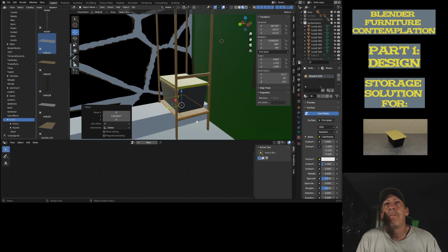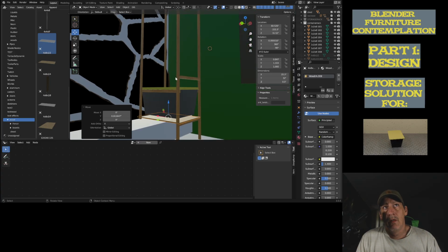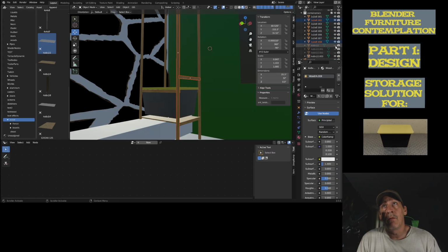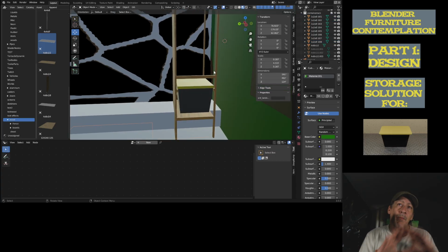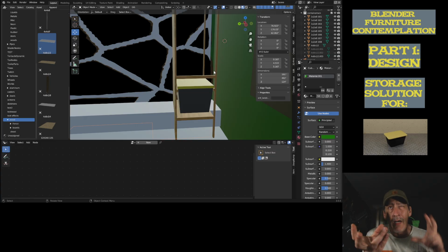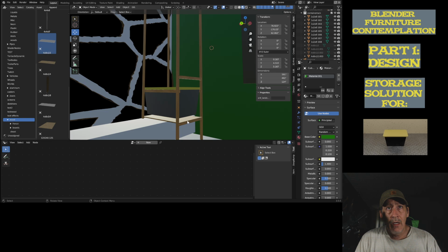So yeah, I think that's probably what I would do there. On these cross braces, especially if we skin it, I would screw from the sides because then you don't have anything showing on the front. So we'd screw into the side, and the face front, our little sheet, would cover those screws, which is another great thing you can plan ahead. Where are my screws going to be? How are they going to show? So yeah, I like this a lot, actually.